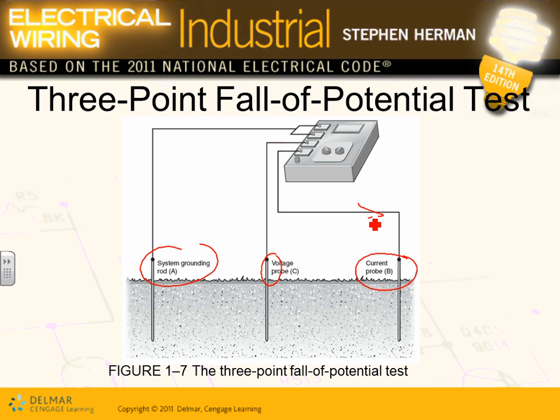They shoot the current into that grounding rod, and again they measure the voltage. They measure the voltage between these two rods, and by measuring the voltage and knowing the current that's going through the ground, same thing, they find the R, the resistance, and they keep driving these rods in different locations. Here's my first rod, second rod. This is the rod for the building, second, third. And they keep going through these, and they keep them as far away from each other, at 80 feet away from each other, in multiple locations, multiple directions.